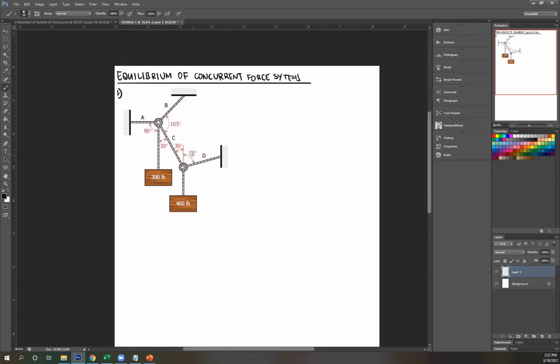So the first step is draw the free body diagram of your illustration. So usually with concurrent force system, you start with a point and then just draw your forces. All of these are cords. So what I like to do is draw all of your cords or all of your wires, cords, string, rods away from your point. So all of them I assume to be in tension.